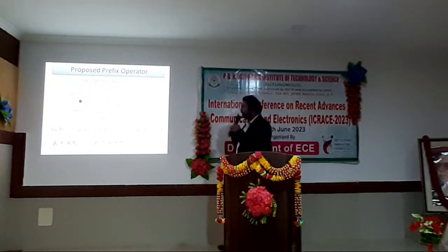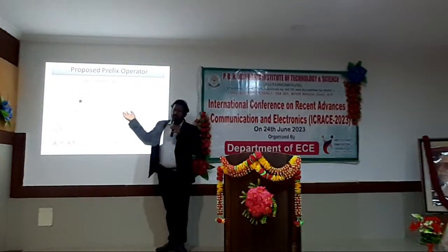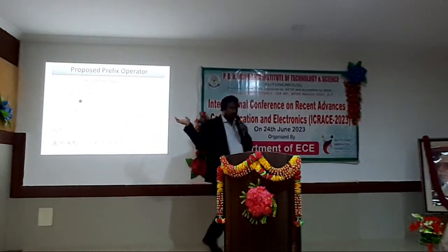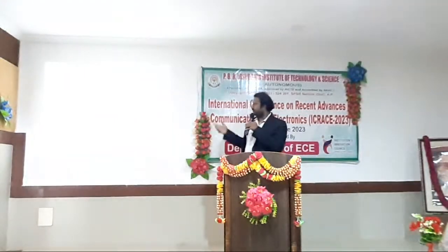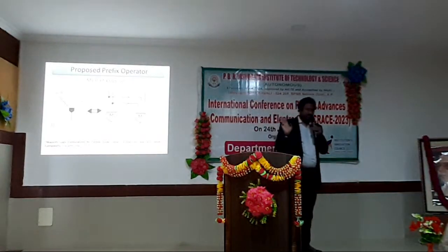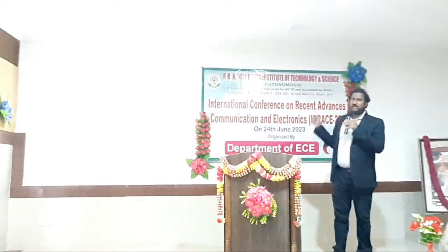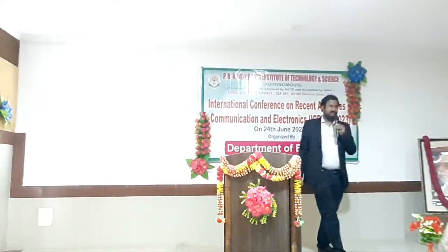So this is the existing prefix operator. It is based on AND gate and OR gate. Majority gates we are using. But what I got is a new prefix operator. This requires only 2 majority gates. It doesn't require AND gate and OR gate. By the way, I got this result after completing my PhD.